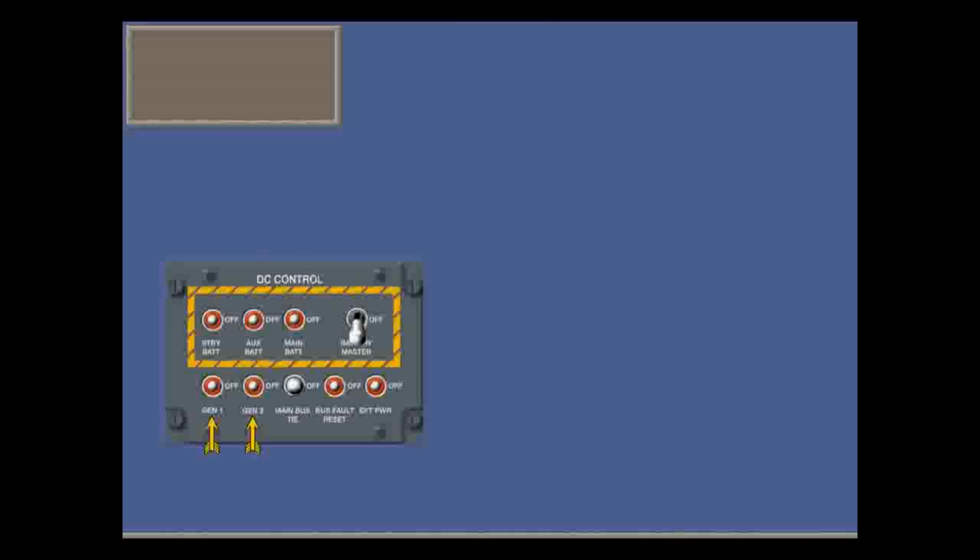These are the DC generator switches. In the Gen 1 and Gen 2 positions, the generator control units are powering the left and right main feeder buses. In the off position, a generator is isolated from the electrical system, and its DC gen caution light will illuminate. The off position can be used to reset a GCU if a generator is shut down. The DC generators are inhibited if external power is on. External power also has priority over the optional APU.